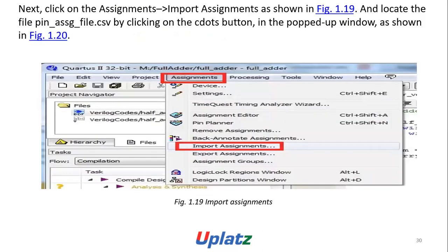Next, click on Assignments, Import Assignments, as shown in the figure, and locate the file pin_assign_file.csv by clicking on the three dots button.